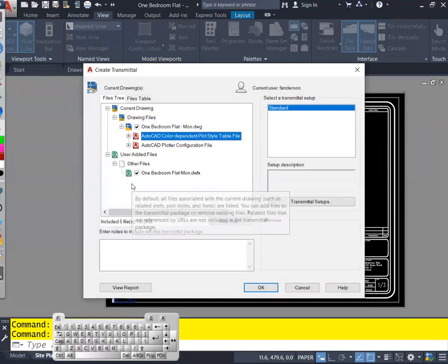So it comes under a different category. This is why I said to you before that the DWG file is not a dependency. That's another file that you would have to add. The only things that are dependencies would have been like your plot configuration settings and your plot styles, or if there was a logo, but because there's no logo, it wouldn't find it here. So if I had a picture on the thing there, it would automatically find the picture and add it here. Yes?